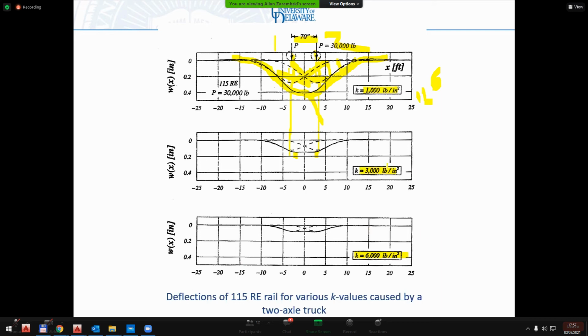So this I said was about 21. This is about 40 kilonewtons. And you can see the deflections, by the way, are significantly lower. The combined deflection here is about 12 millimeters. The combined deflection here is about 3 millimeters or 2.5 millimeters. And this is sort of in between. This is about 4 or 5 millimeters.